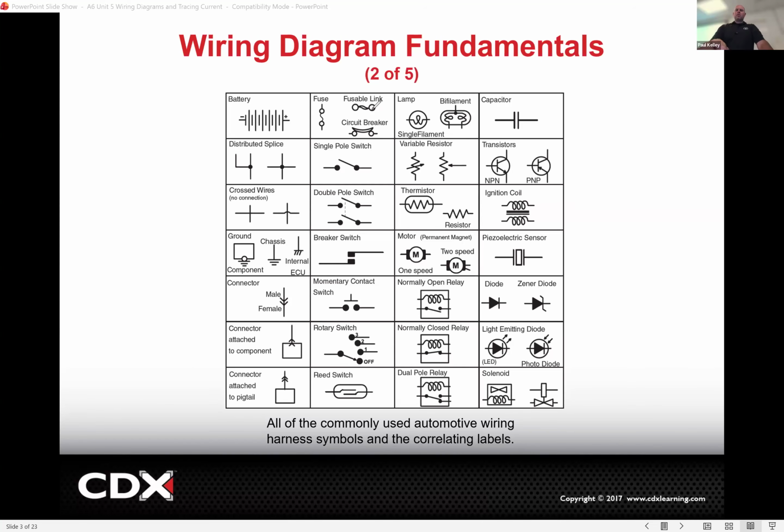And then with bulbs, they can vary a little bit in design, but overall, this is your typical bulb. Have you guys ever seen dual filament bulbs? That would be pretty common for like a tail light, stop light. So the tail light might be this one, and that would glow kind of dim. But then if you apply the brakes, the more bright stop lamp filament will glow, and that'll make them brighter. So if you come up on a car and you see that the red lights are on behind it, you're kind of like, are those brake lights or tail lights? And then if they step on the brakes, they get a lot brighter. That's how they do that.